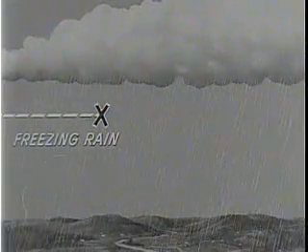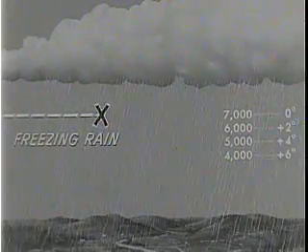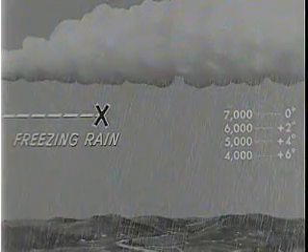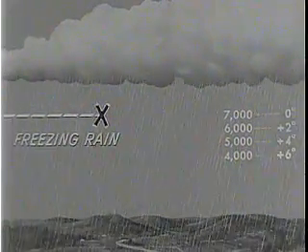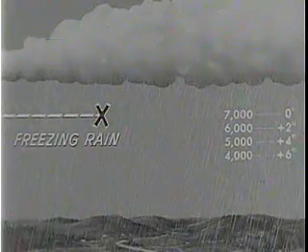Judging from the information gained in your pre-flight weather briefing and knowledge of the standard temperature lapse rate, you may find there is above freezing air below. With ample terrain clearance, descend as rapidly as possible to the lower altitude.